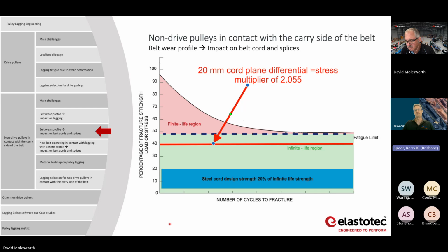Really stressed belts are probably not head drives, although the Tolgoi does have a head drive. And so that splice length, I think, is also a little bit compromised, and certainly the transition is. So that could be one that we could run. So what do you think of this one? Because that's brand new and it's only just been started up, and we haven't started nudging the safety factors on that belt yet because they haven't been running at design throughput.